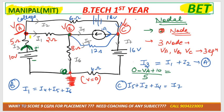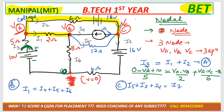Like I1 is moving from VA to VB, right? So it would be VA minus VB divided by 2. Again, I2: I2 is moving from VA to VC. So it would be VA minus VC, and for the battery we have to take the second sign, minus 18, divided by the resistance, that is 6 ohm.